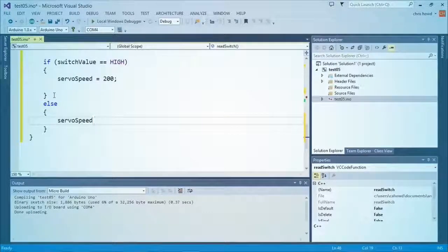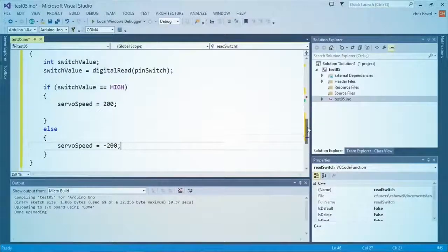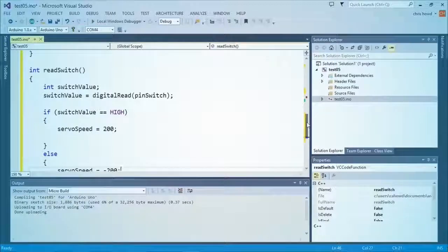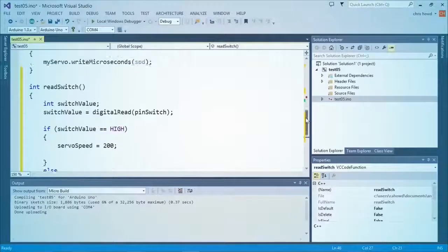And you can use that switch to turn the machine off and on if you wanted. We're using it to change direction, correct? You can do whatever you want. You read the switch, it has a value, you decide what you want to do with it. It's very versatile. But we're just getting this concept of holding a pin high. We're setting pin mode to set whether it's input or output. We're then doing digital read and digital write.